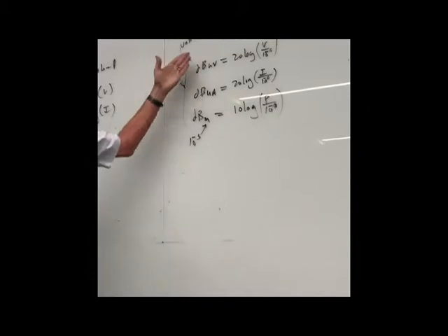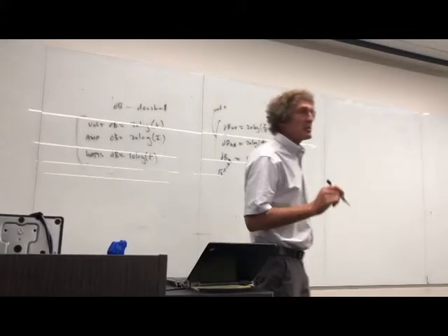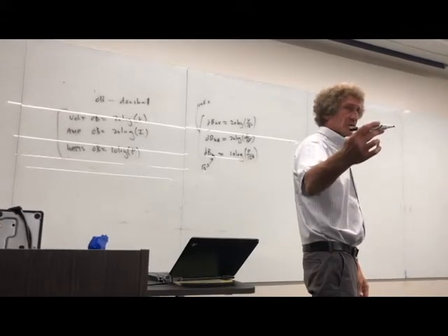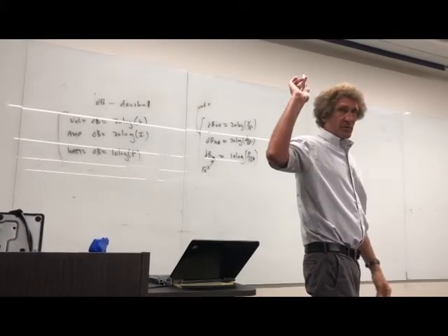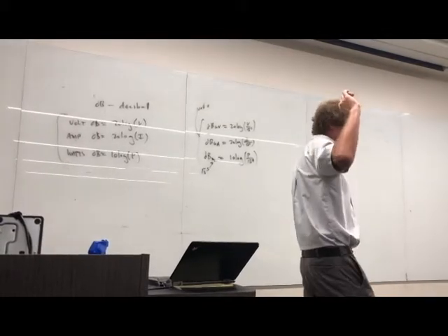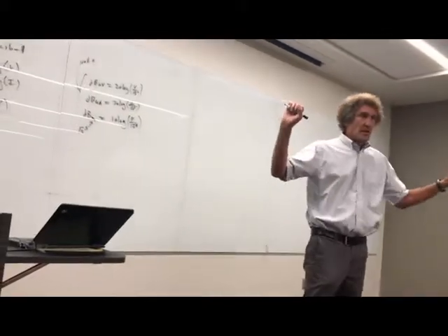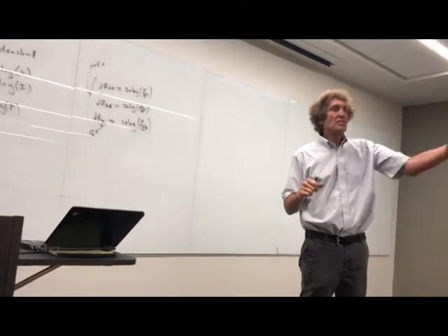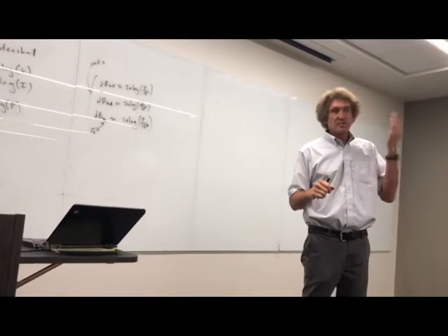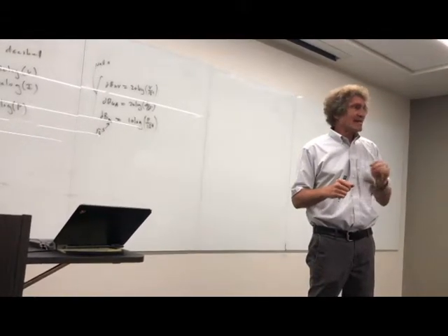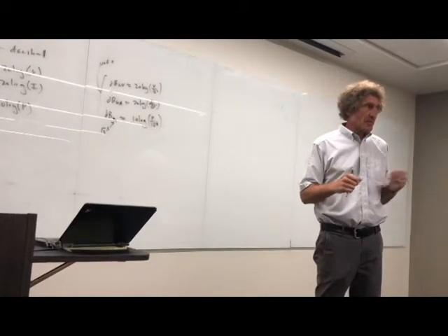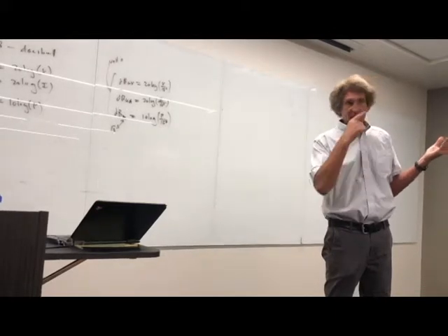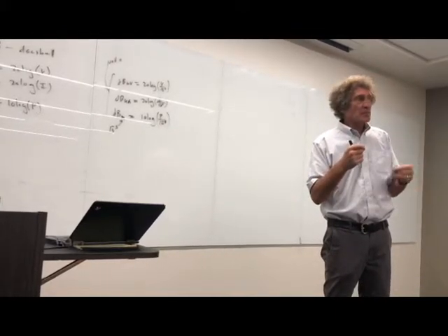Now, these are units. There's another thing that's commonly done, and it's talking about how many dB of loss occurs. How many have heard that kind of terminology? You know, when you get cable, like coaxial cable, it's rated as like 4.5 dB per 100 feet at a certain frequency. As the frequency goes up, or basically doubles, it'll be rated at 9 dB per 100 meters, all right? And what they do with cable, most cable, is give loss in either per 100 meters or per kilometer.